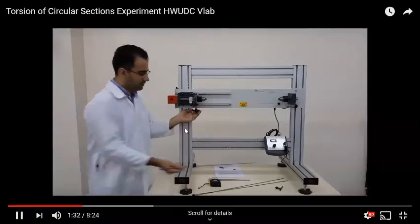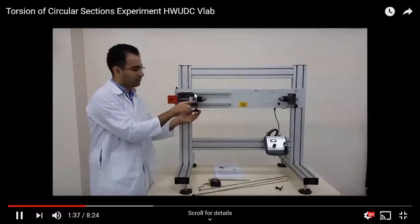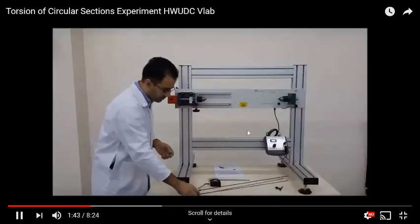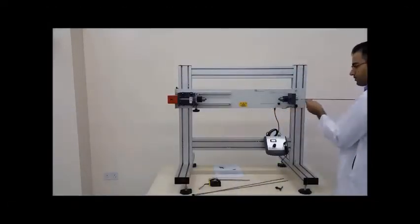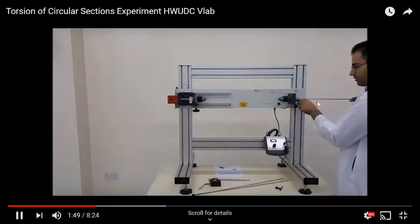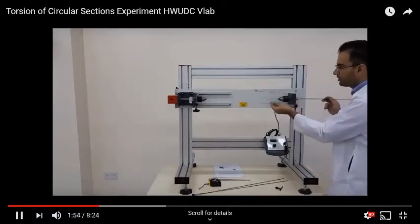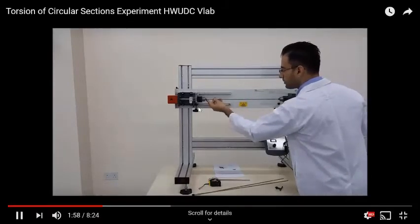He said before you put the rod in the equipment, you need to adjust this to 0. So this is what you're going to be reading as your angle of twist. So you need to make sure that was 0 before you start. And then you insert the rod on this end, and into the chuck on this end.